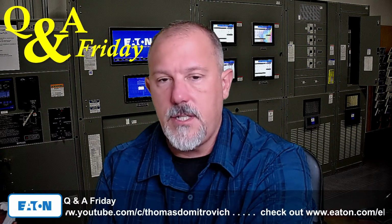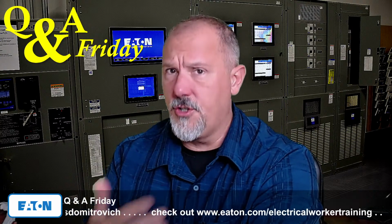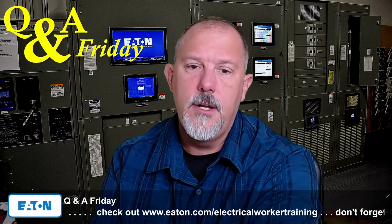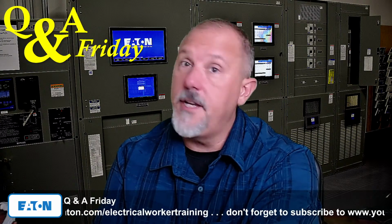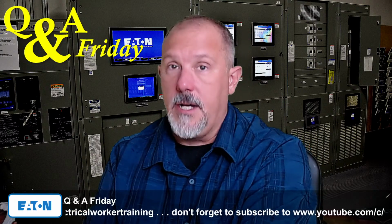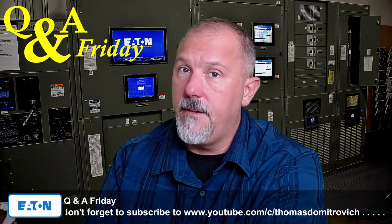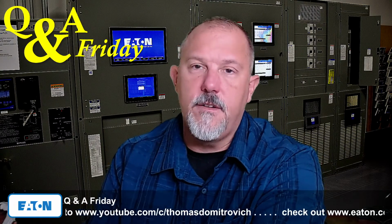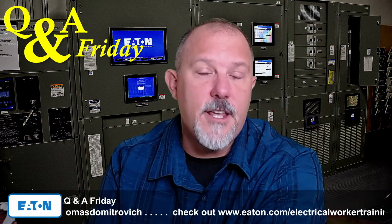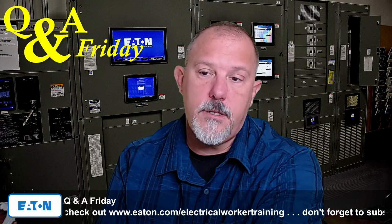The challenges that I've seen are not necessarily in small equipment. Your larger HVAC systems and things of that nature are where your challenges are. Now, having said that, I've seen some GFCI receptacles being misapplied very close to service entrance equipment, and the available fault currents are greater than 5K or 2K. If you understand the ratings of the GFCI receptacles, components like that are very easy to misapply,